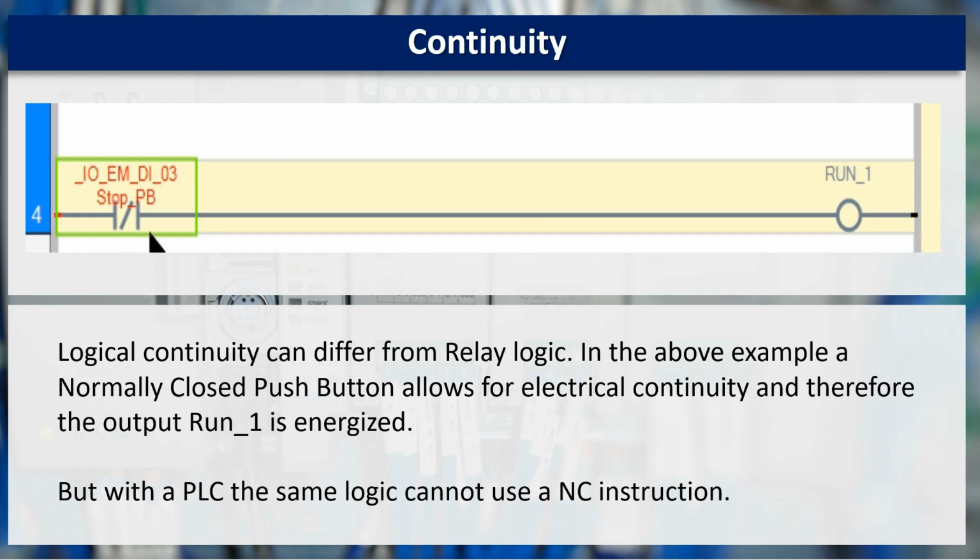This is because this instruction tells the PLC to go look for the absence of voltage, a 0. It found a voltage, as can be shown by the red lettering, which is not the correct response that it's looking for with this instruction. Therefore, it's false, which means the output must be false.